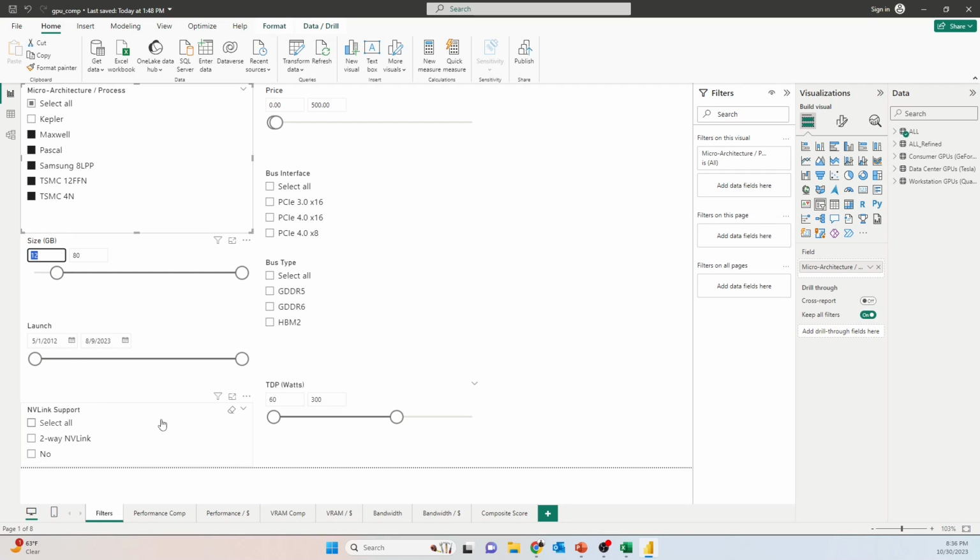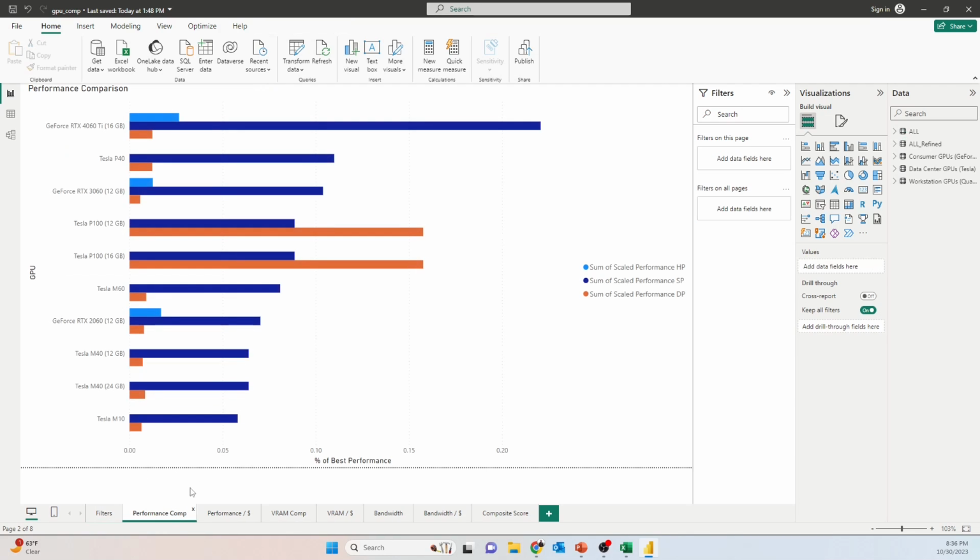And then I have a maximum constraint of 300 watts because I'm going to try to put these GPUs in a Dell PowerEdge server, and unfortunately the risers and the 12 volt EPS on both of the risers combined max out at 300 watts, so it limits the upper end of what I can put in there. Okay, so with that in mind, let's go look at the performance.